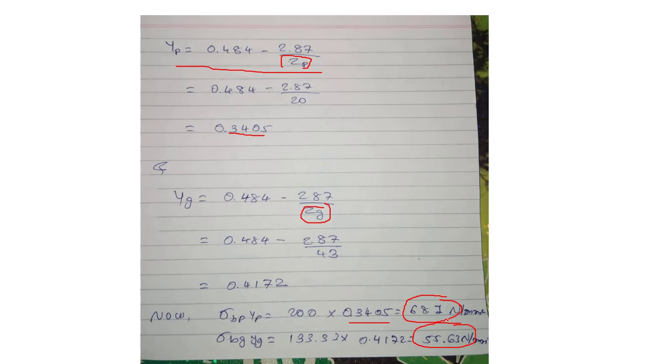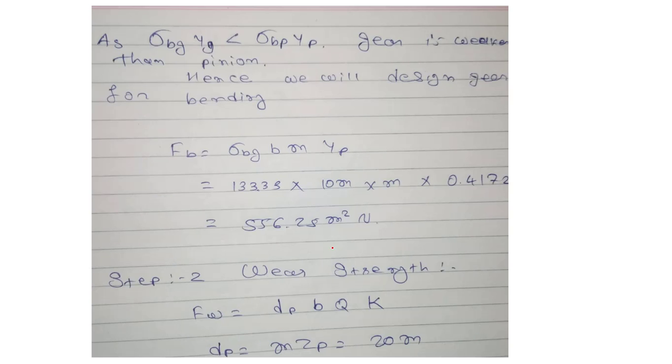From both values we easily conclude that the gear is weaker than the pinion. Hence we will design the gear for bending.